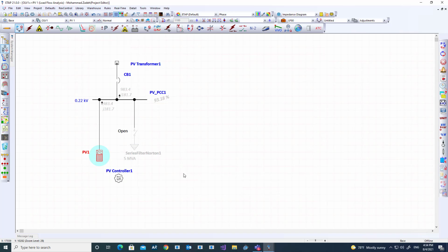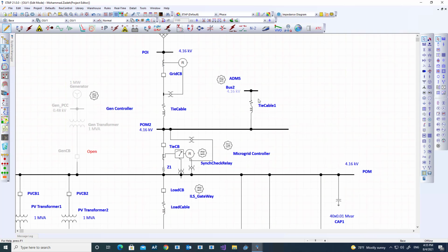Okay, so now that I have my inverter set up for the short circuit, I can easily do the short circuit analysis. I can put the fault at the bus, or I can put at any fault location to do the analysis. So let me just go ahead and put the fault somewhere in the system. I've created some kind of a dummy cable to place the fault. So if the fault is in front of an inverter, voltage drops to 0, it gives a full current. Most of the times you want to analyze when the fault is on the system side and see the contributions, how the directional protection works and things like that.